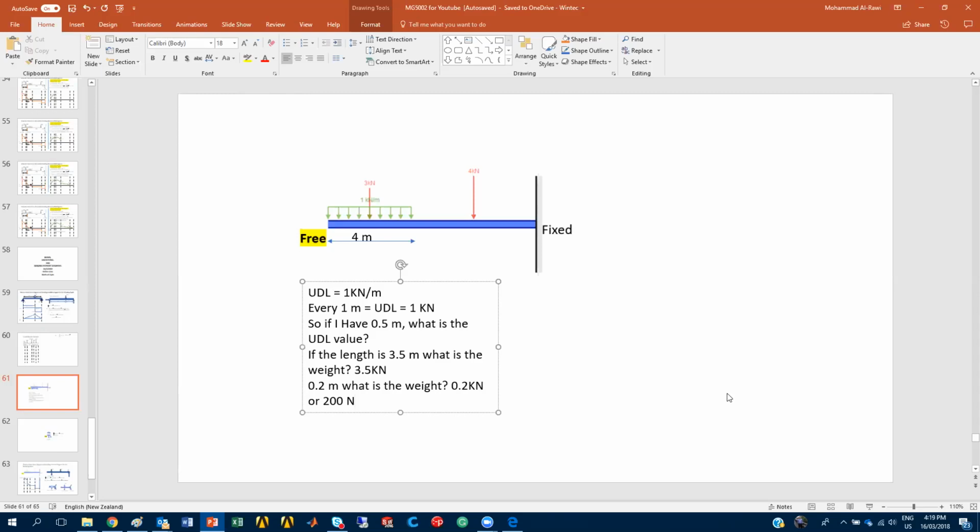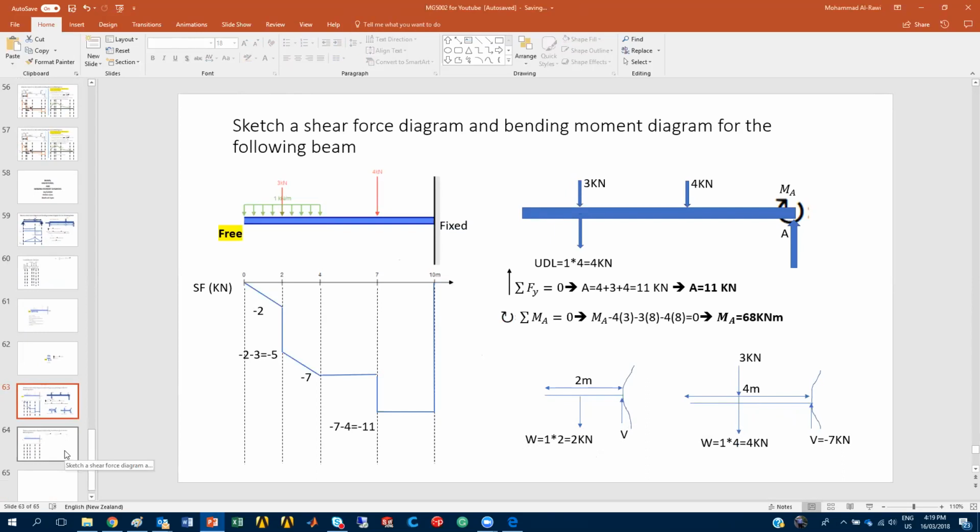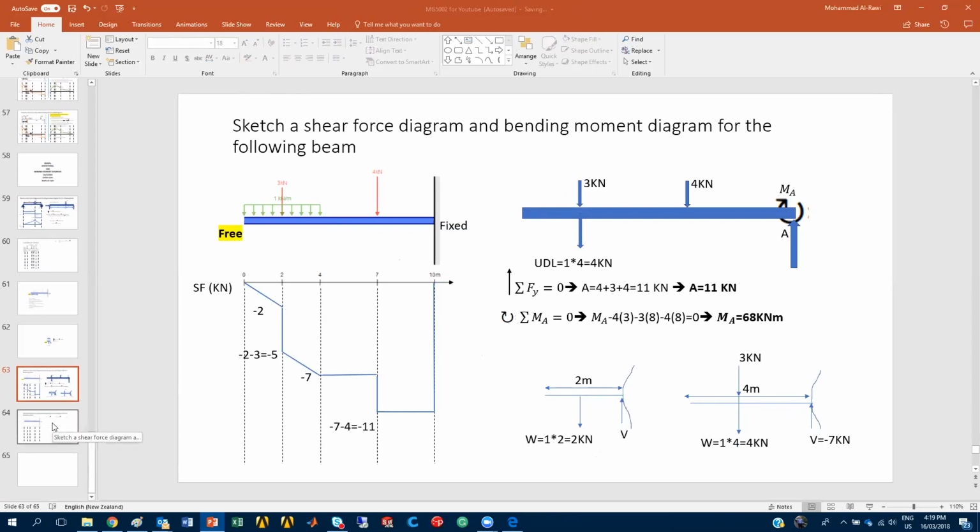Good, that's perfect. So let's go back to the question. Since we took the shear force, every time you can take a section to find the value of the weight. Maybe here, to stop confusing you, we can write weight, W. Make sense? Then you determine the values and find the shear force. That's exactly how to find the shear force. Can we repeat the same steps to define the value for the bending moment, or the diagram for bending moments?